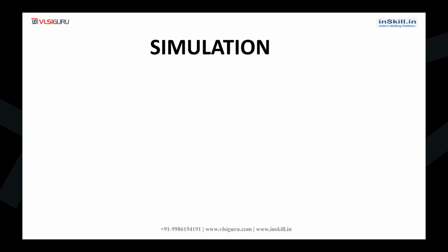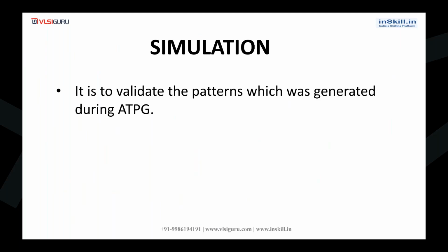Now after that we have simulations. Simulations are to validate the patterns which were generated during ATPG. Before delivering the patterns generated during ATPG to test the chip after manufacturing, we need to validate whether proper patterns are generated or not.